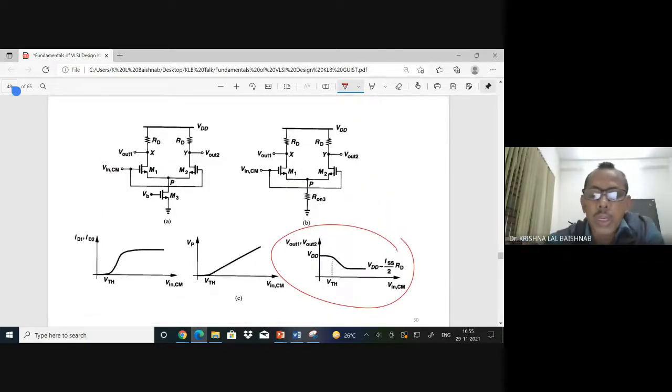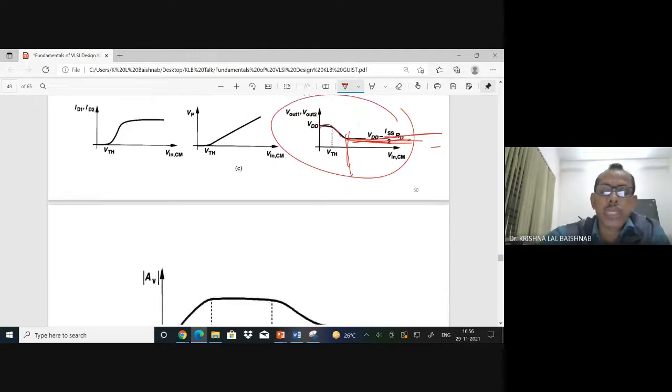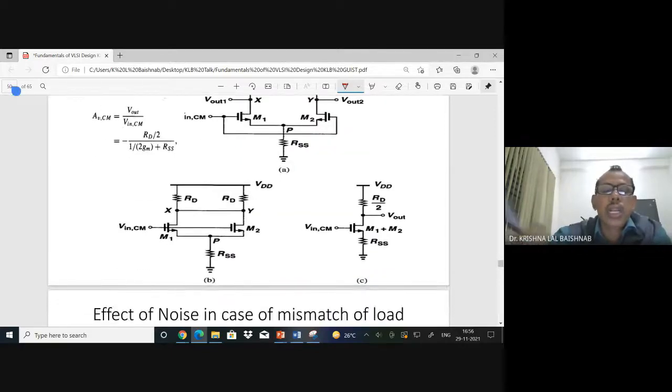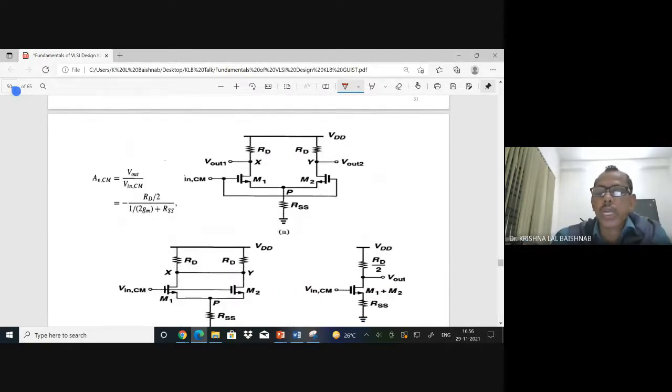Many times we say common mode voltage. You see that the common mode voltage becomes stabilized at this point. We cannot take an arbitrary voltage. We can take the common mode voltage from this to this. But we should not take common mode voltage over here because this is instability. So the common mode voltage should be from this to this. Please study from Razavi's books. Very fantastic, they have explained where we can fix your common mode voltage in this range. You can fix your common voltage and change. Then there are different combinations we can really work out.